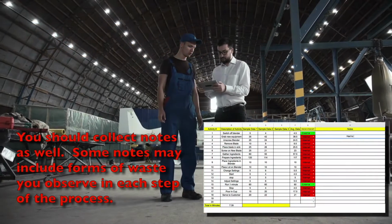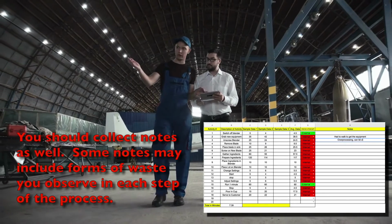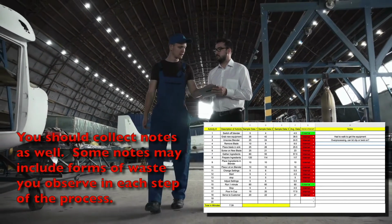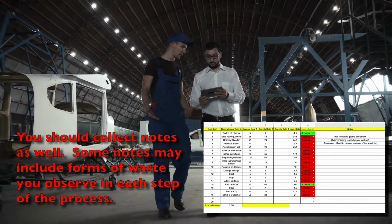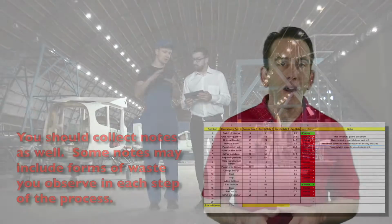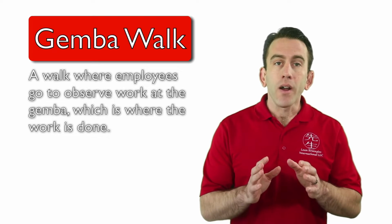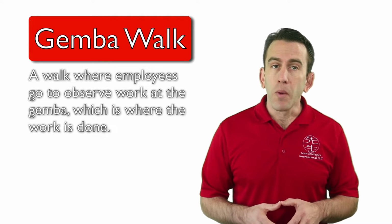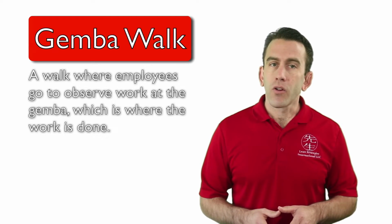In addition to data, you should collect notes as well. Some notes may include forms of waste you observe in each step of the process. A good way to ensure you collect the right data and notes is to walk the value stream forwards and backwards as you decide on what forms of information will help you accomplish your goal. This is referred to as a Gemba walk. While walking the Gemba and reviewing your improvement opportunity, look for some of the following setup and changeover characteristics.